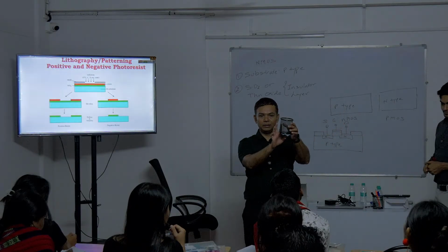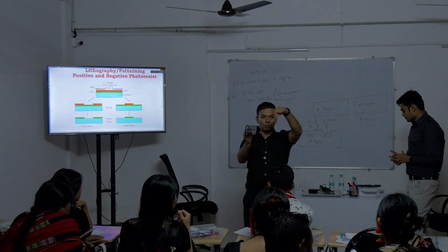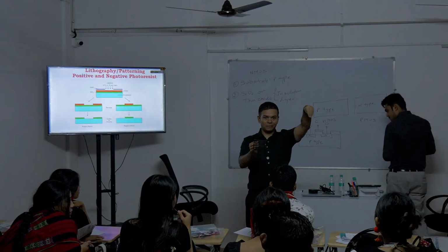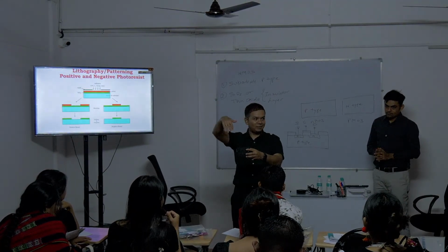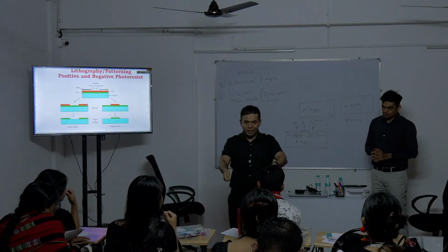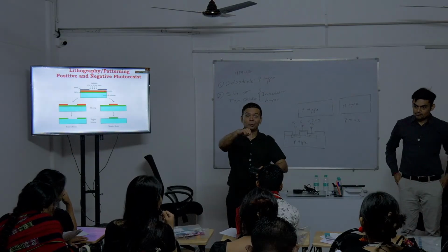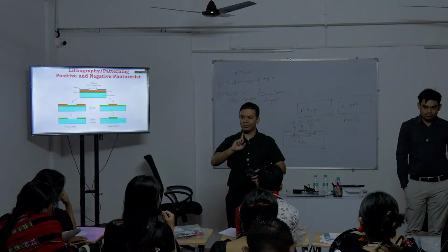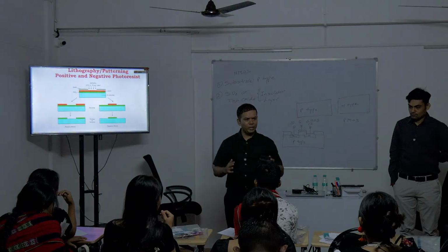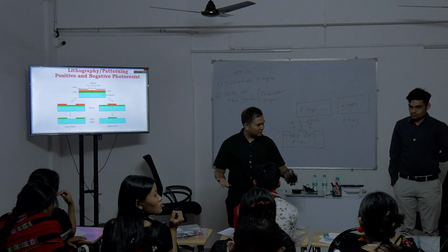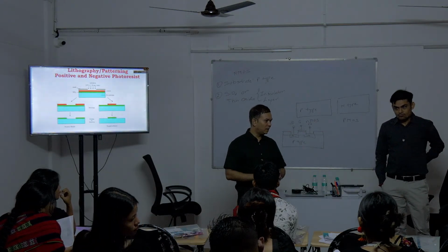Let us say this net is there, right? If I just open it, there are some nets and there are some holes. So if I put sand, don't you think the sand will only go to the holes, while wherever there are nets, that will be left? So when I pick up this one, you will have a very good pattern with the sand only present where there are holes, and no sand wherever there are nets. Are you getting? Same thing is over here. You're just doing it through some complex process, which is known as photolithography. That's all. Understood?